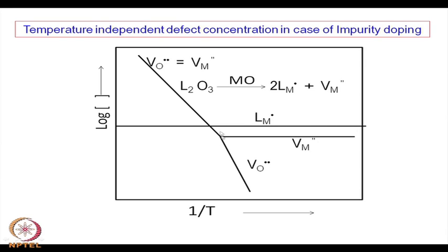There is no activation energy here, whereas there is activation energy for the higher temperature. So, this becomes the intrinsic region and this becomes the extrinsic region. Of course, it is only the concentration that has been plotted here. If you plot log conductivity, the other term also will come in, that is the mobility term. So, mobility may change, and therefore there will be a slight slope here.